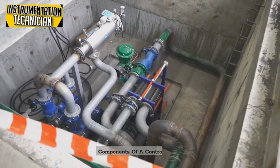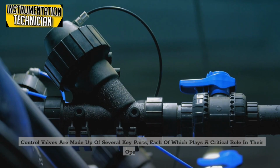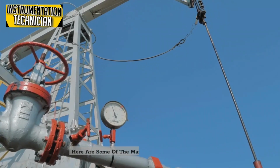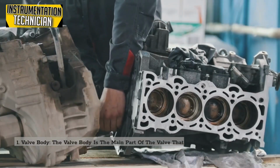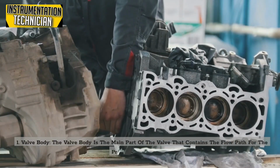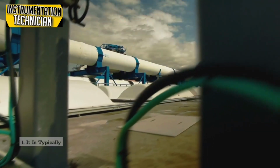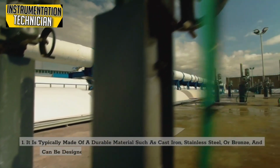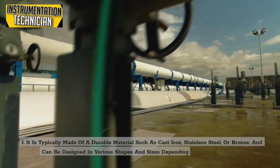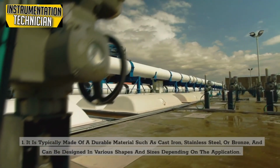Components of a control valve. Control valves are made up of several key parts, each of which plays a critical role in their operation. Here are some of the main parts of a control valve. 1. Valve body. The valve body is the main part of the valve that contains the flow path for the process fluid or gas. It is typically made of a durable material such as cast iron, stainless steel, or bronze, and can be designed in various shapes and sizes depending on the application.